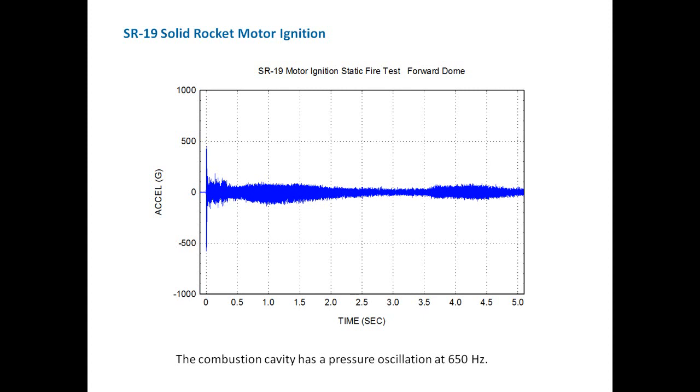And just to back up a little bit, I think we've talked about these types of thrust oscillations before, but basically the combustion cavity of the motor is a hollow space, and in some cases it can act like an organ pipe. But anyways, standing pressure waves can set up in that internal cavity geometry as driven by vortex shedding and other effects. And some solid rocket motors have very prominent thrust oscillations, and others don't. And who knows why some do and some don't? I don't know.